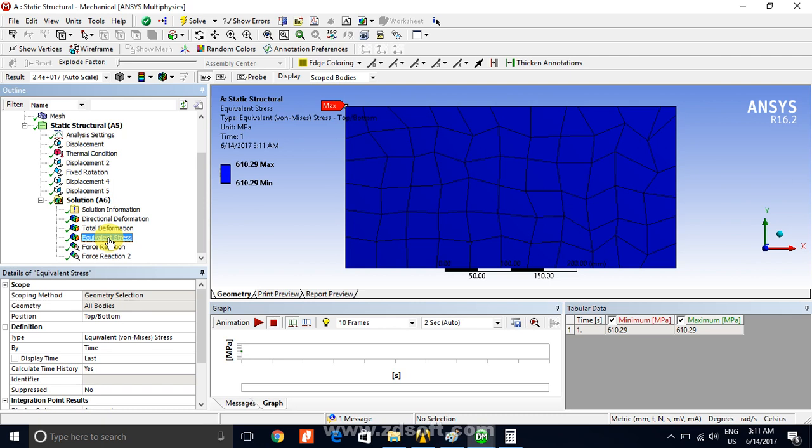This is actually the closest to the real, not just close, this is the actual value which is coming in the body. Therefore we have modeled the FEA model as the real body, with real deformation phenomena, and how the body is really going to behave. If we apply the incorrect boundary conditions, you will be in trouble, and you will think, what is this, this high stress of 1000, 2000, what is that? And you will get confused. So be aware when applying boundary conditions.